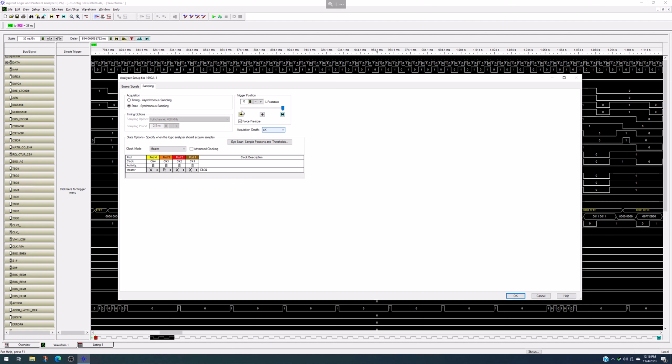So obviously it's got a FIFO or something that it's internally using, so that as all this data is running, it's keeping track of when the trigger happens. It then says grab the most recent 4K of data, and that's what I want to then show. Or you can place this wherever you want. Maybe you want half of the data prior to the trigger, half the data after the trigger.